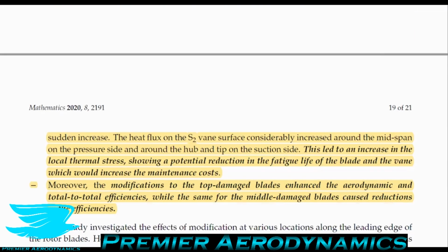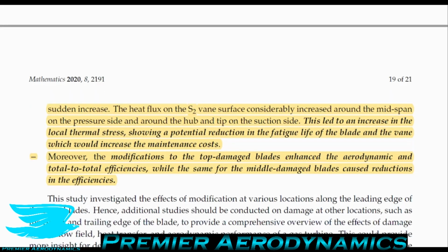On the rotor blades, the heat flux around the damaged location exhibited a sudden increase. The heat flux on the stator blades surface considerably increased around the mid-span on the pressure side and around the hub and the tip on the suction side. This led to an increase in the local thermal stress, showing a potential reduction in the fatigue life of the blade and the vane, on the rotor blade and the stator blade, which would increase the maintenance costs. Finally, the modifications to the tip damaged blades enhanced aerodynamic and total efficiencies, while the same for the middle damaged blades caused reductions in the efficiencies.